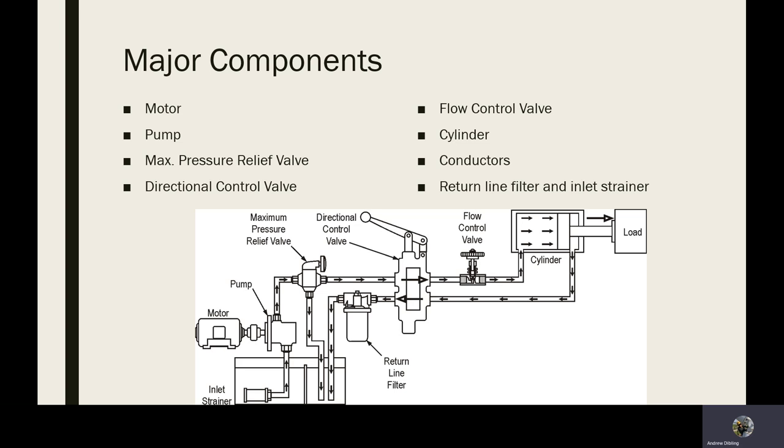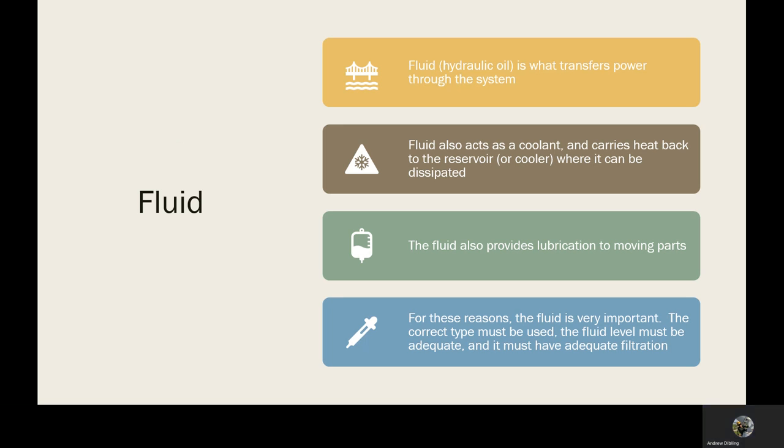This is a spring return spool valve, and it has two directions. It can make the fluid flow in this direction, or it can make the fluid flow straight across, crisscross, or straight across. And a lot of times, these ones will have a cycle back to the tank when not in use. So the fluid is constantly being circulated, filtered, and viscosity is maintained because it's always moving. A lot of advantages to keeping the system moving. The cost of it is going to be the cost of your electrical power, right?